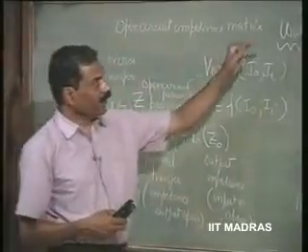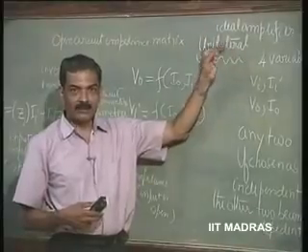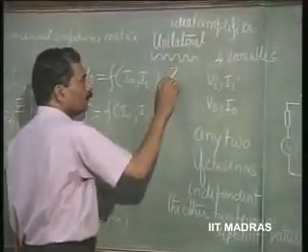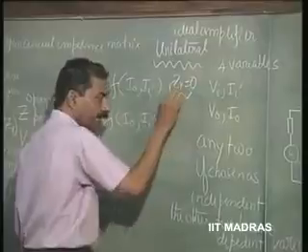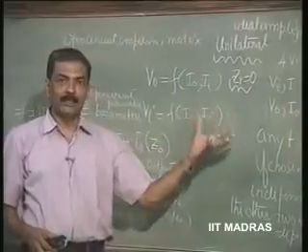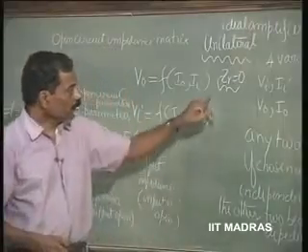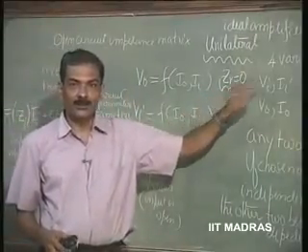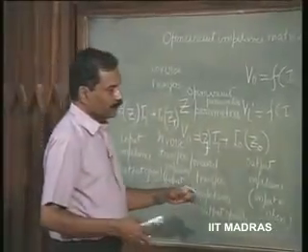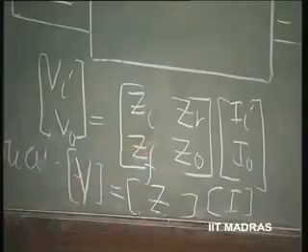That means in any ideal amplifier represented in any fashion, in any matrix, the reverse transfer parameter is 0. That means Zr is 0. So I am defining it and then making it 0 in order to illustrate what is really an amplifier represented in a two-port theory. So the reverse transmission should be going to 0. Now, if reverse transmission is 0, Zr is 0, and Zf alone exists, and what about Zi and Z0?